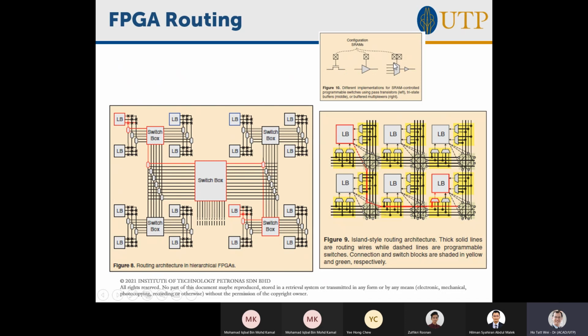But I would like to alert you that this switch is nothing else but a bunch of multiplexers that look like this. Either you can think about it as a pass transistor: you turn this on, the logic goes through; you turn this off, this is floating. Or a tri-state buffer, which is the same thing: you turn this on, this is true; you turn this off, this is not going through. Or you can think about it as a multiplexer, which is buffered. You choose which of these outputs goes out here. They're kind of equivalent and they'll be implemented in different ways, but it's just to let you know that the switch is not something magical. It's comprised of all of these. So you're just choosing which wire connects to which wire using one of these configurable switches.